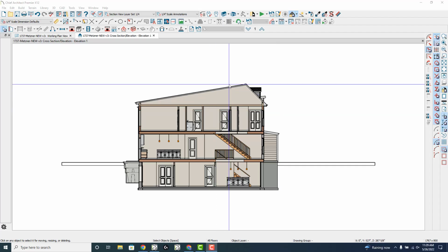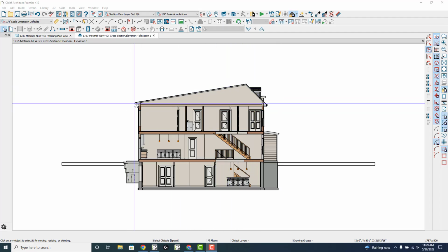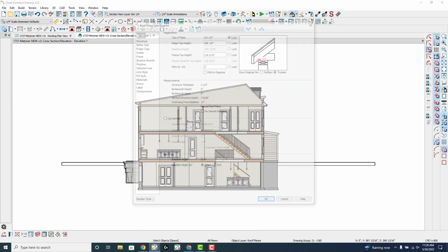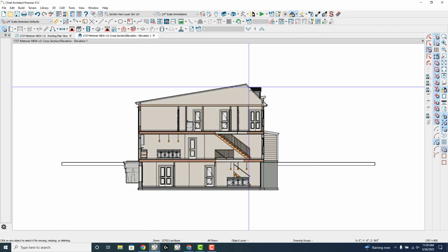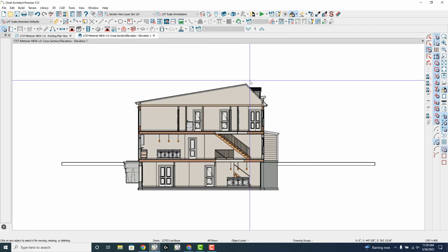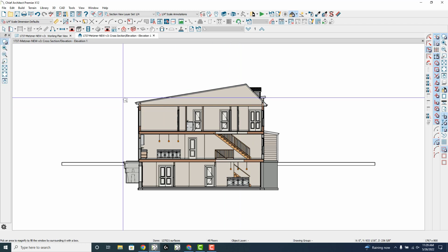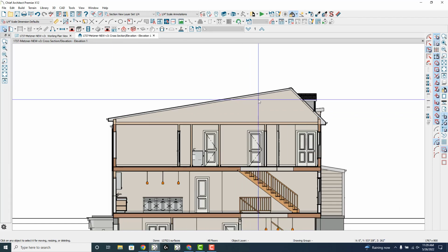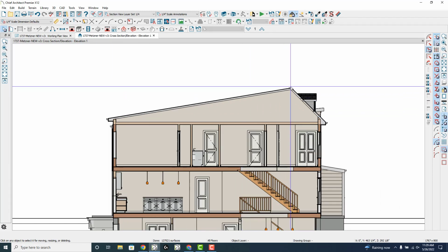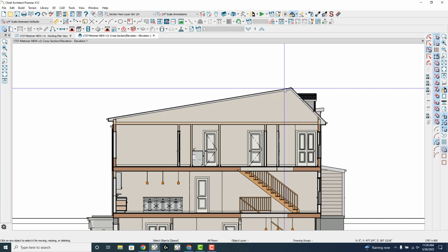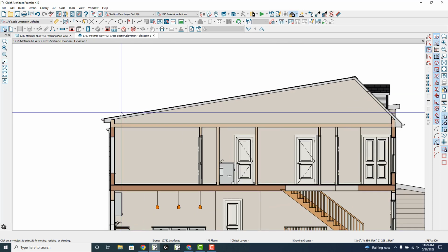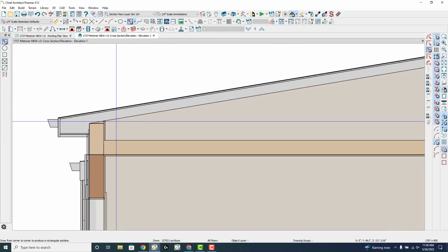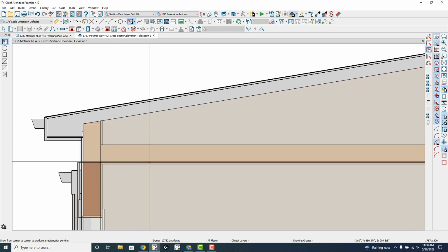So I currently have this roof here where the low slope, I believe this is a 2/12 pitch, yes, and a 12/12 pitch on the front, currently meeting at the ridge. I want to do a couple things with this. I want to make sure I have a 14-inch energy heel, and I need to have that 2/12 be about 8 inches taller than the 12/12 so that we have proper flashing and capping details.